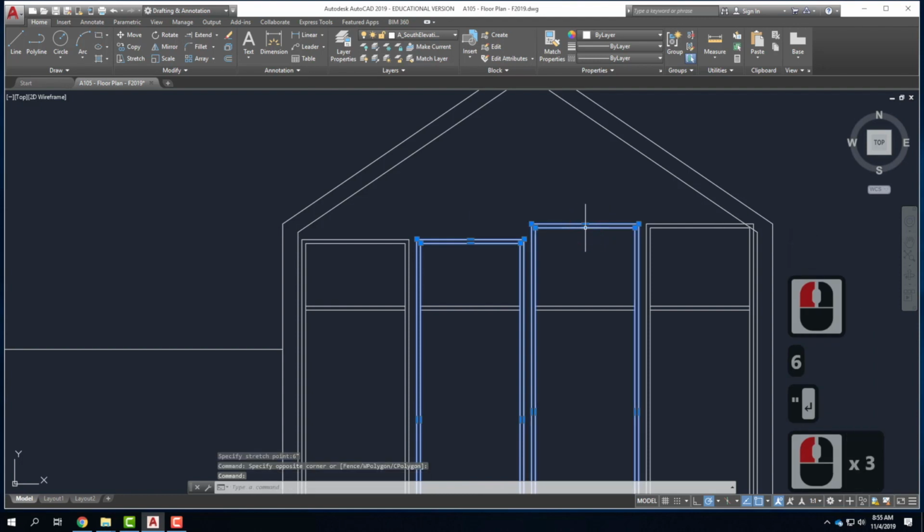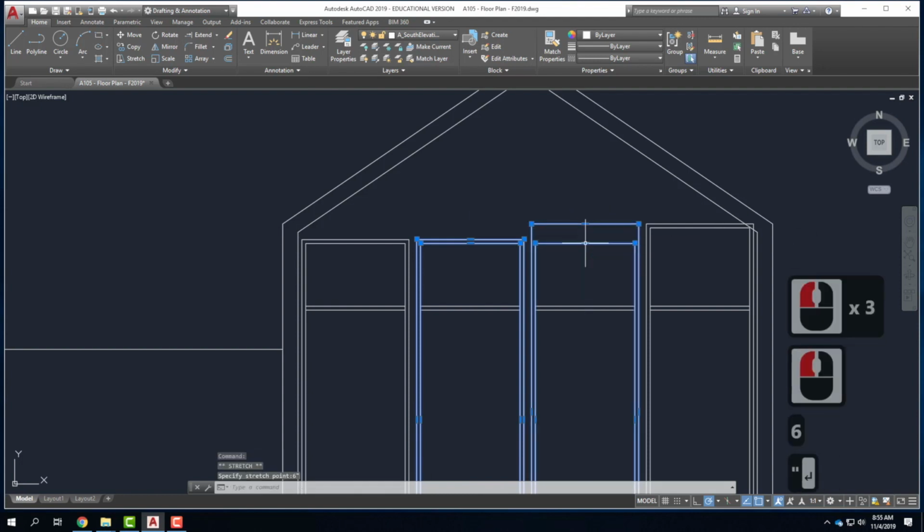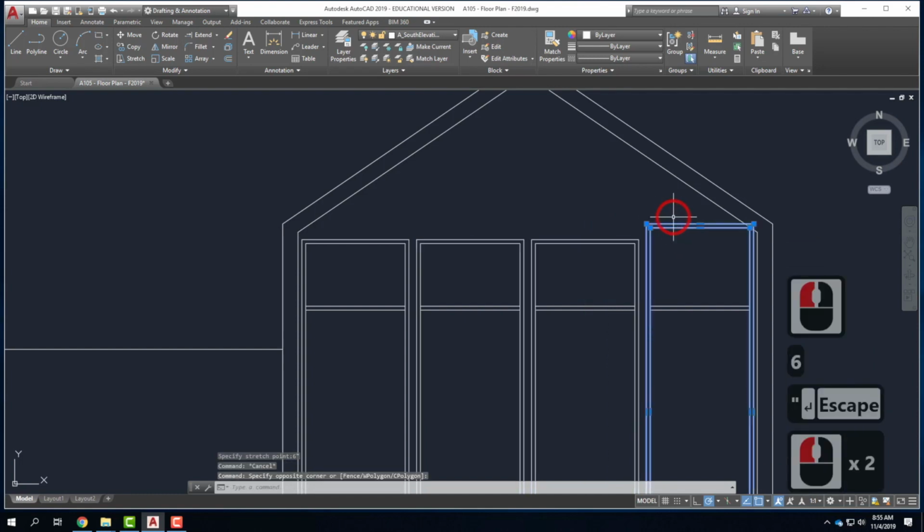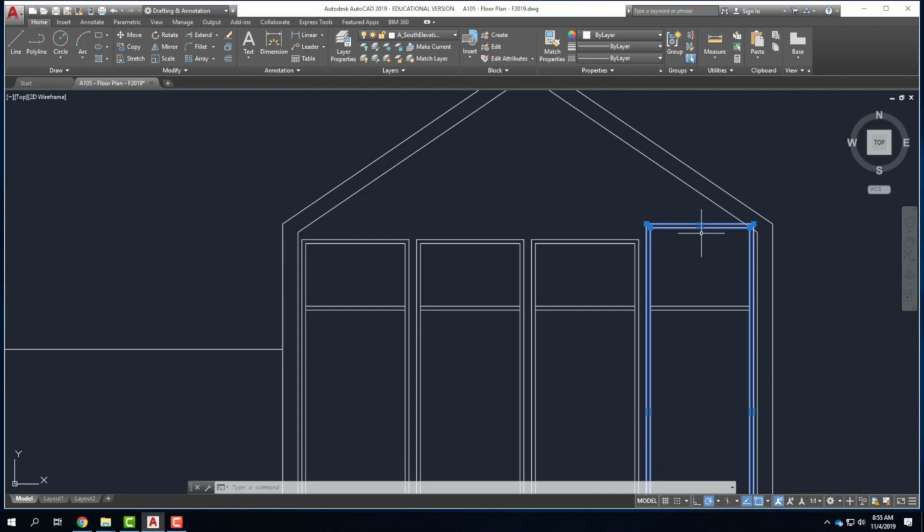How come, when you're offsetting the roof, you offset it inside instead of outside? I could have done it outside. Yeah, you can absolutely do that. I'm not actually being perfectly technical about how you would determine where the roof is. It has to do with the wall and the plates and what the bird's mouth looks like. There's a lot of technical detail to the section that we could go into, but it's just not relevant for you guys at this point. So I'm doing kind of basic. Just go from the corners and come up. Usually you would have to add, and the roof would be taller than where your ceiling height would be.